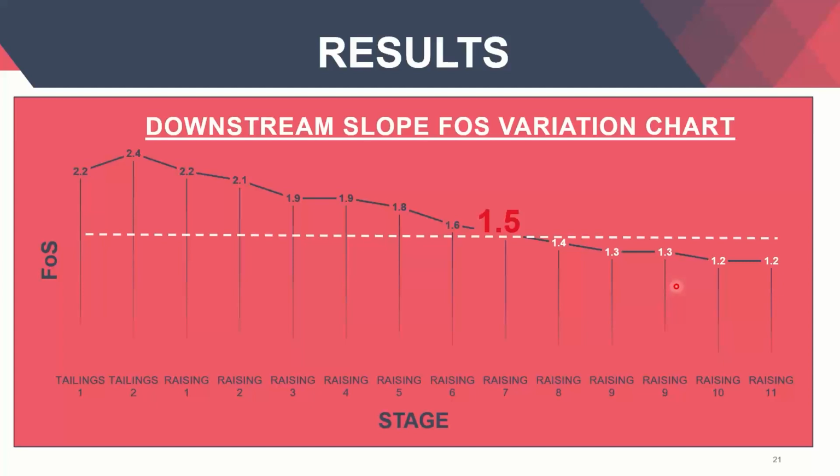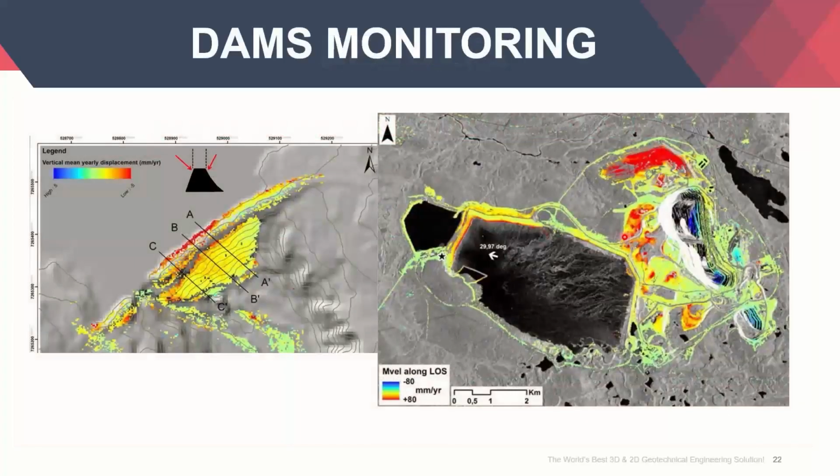So now you have checked the displacements, you have checked the pore pressures and the factor of safety. So these dams are built, as I mentioned, for the next ice age. So the question is, how do you monitor it? A lot of you are aware of extensometer readings or inclinometer readings, but nowadays there is a new type of monitoring equipment, that is the InSAR modeling. So the InSAR results look like this.